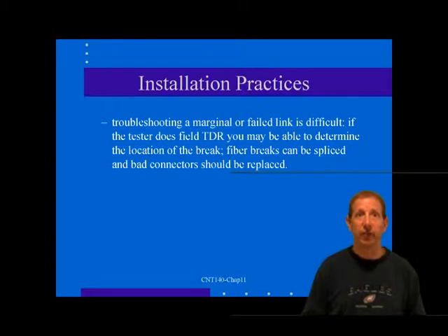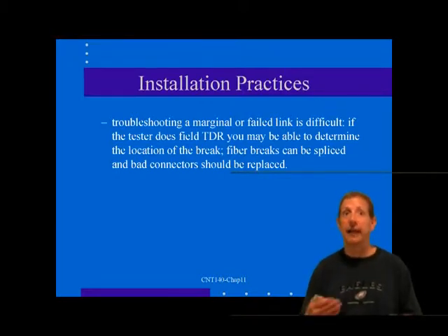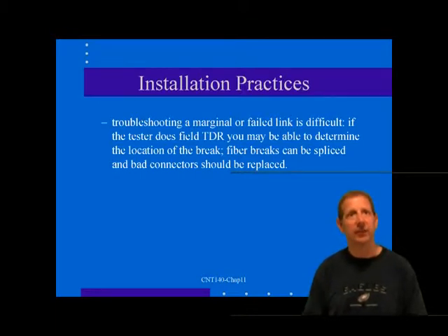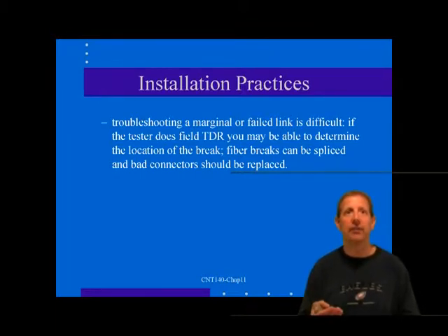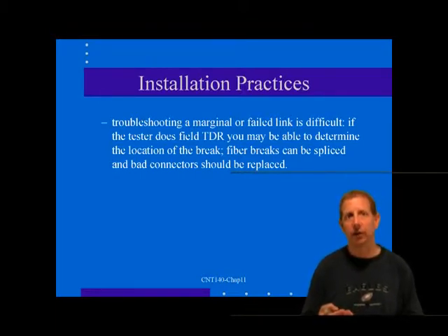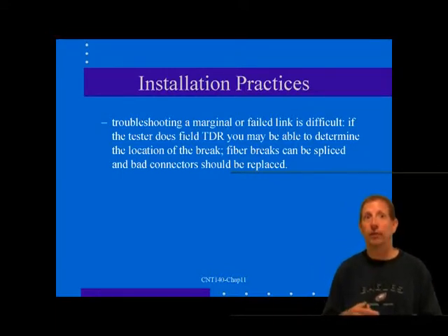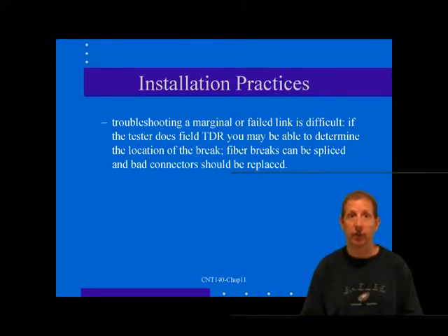The local unit sends light of a known intensity down the cable under test. The remote unit senses the absolute magnitude of the received light and then calculates the loss. A pass-fail indication is made and may be a function of the length of the cable. The remote may be totally passive to the installer and simply report the results of the local tester.